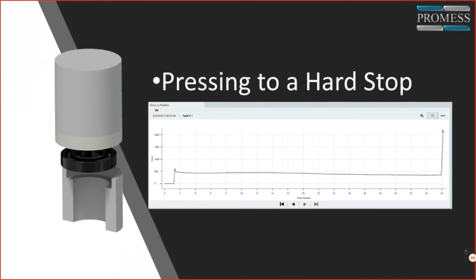When pressing to a hard stop, this method allows the system to continue pressing until it achieves the desired force. Typically, the force that you press to is more than what it actually takes to press the part, but you want to ensure that you've fully seated the part.